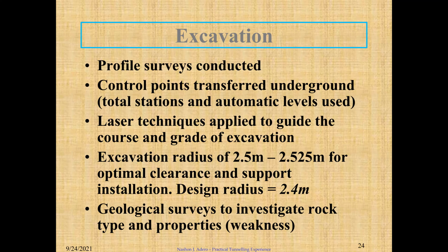So if you have a laser, you need laser machines, and this beam will not just be beaming anyhow. A surveyor has to set it up. You have to set up the laser equipment such that it is giving you a line of sight for reference, and this laser beam must be surveyed to have the slope that is designed according to the slope of the section being constructed or excavated. So the beam itself should be sloping, and the beam itself should be going in the right direction. So the beam also needs both vertical and horizontal alignment.